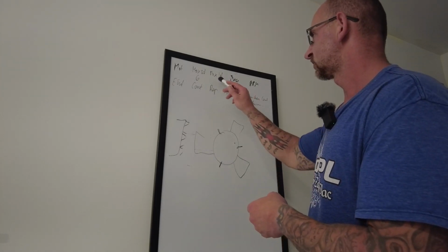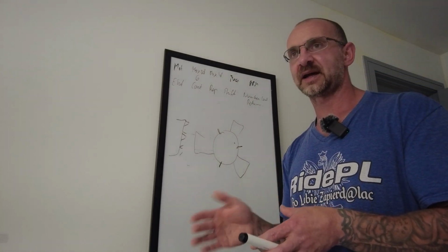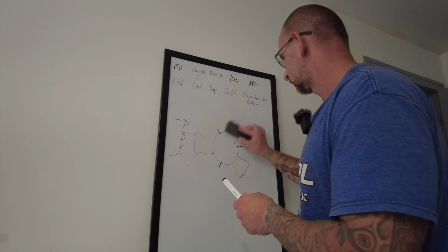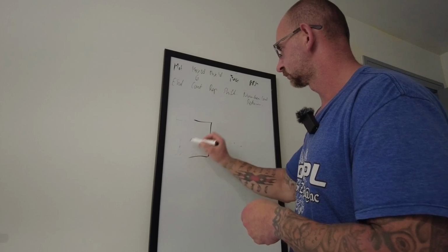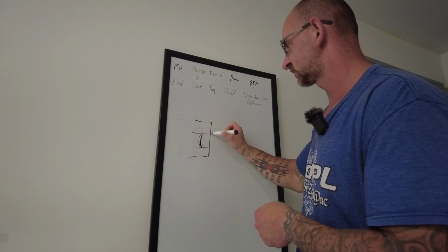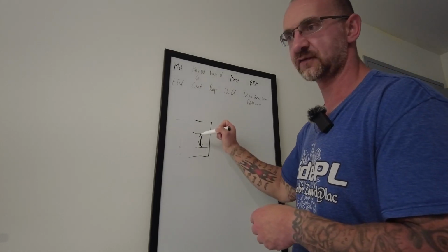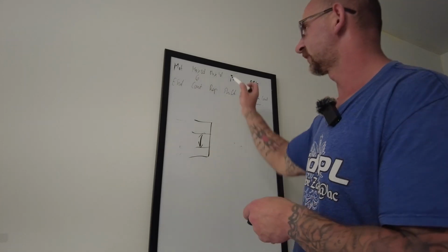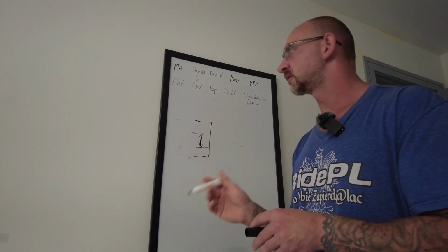Now, when it comes to your ID, it doesn't matter if I already have a hole 2 inches or 3 inches and whatnot, I always set it to 0. For the fact is that if you have a 2-inch hole, you're gonna tell her to start cutting at 2 inches. She will not come down to 0 if your minimum ID is 0. She'll only retract, let's say 40,000, then it's gonna come out and go home. So the clearance on ID does not reflect necessarily the ID. That's why it doesn't matter if I have a hole or not, I always use a 0 anyway.